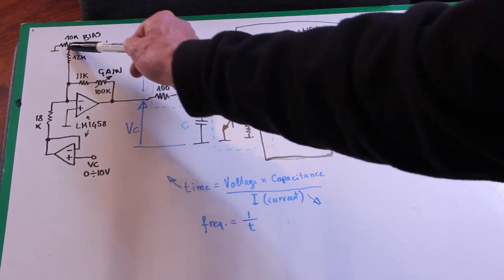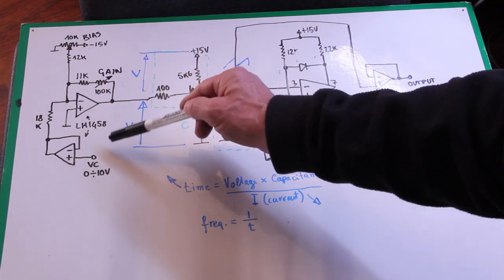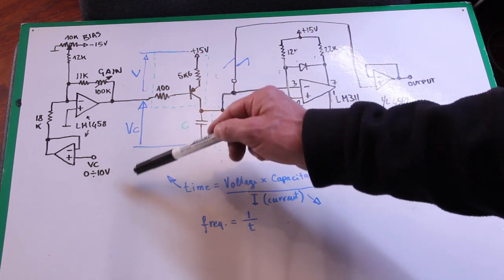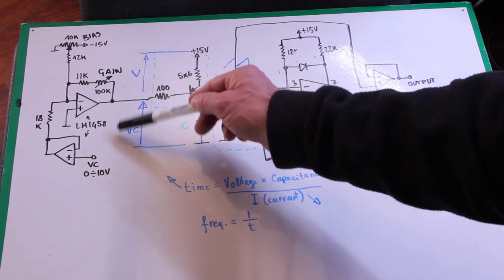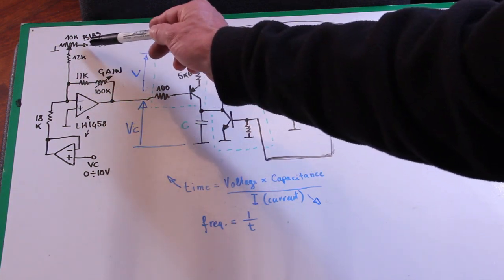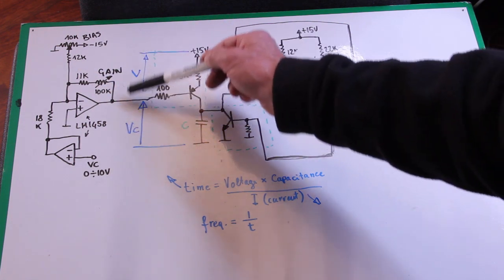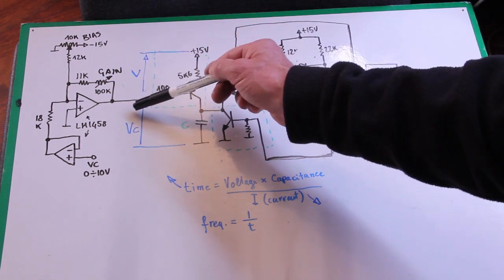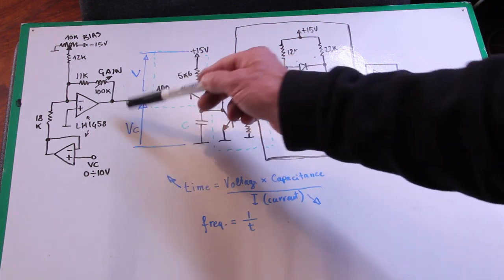First we turn this completely to 0 and adjust the gain for the full range of voltage required to control this transistor, about 4 volts, and then we adjust the bias in a way to correct this voltage and put the minimum voltage here at 4.3 volts. Okay, now we have a nice sawtooth generator. So let's see how to make it work at its best.